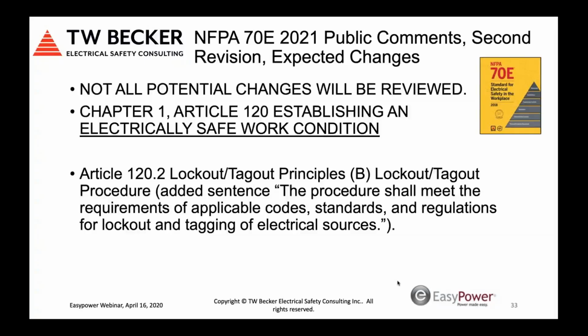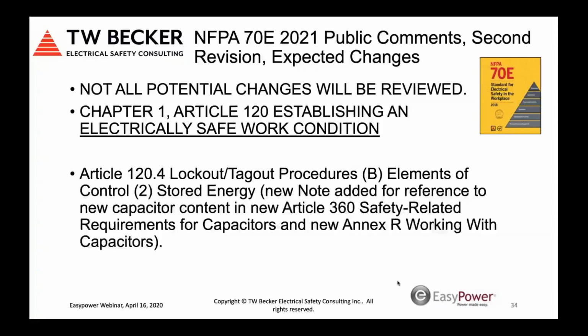Article 120.2, lockout tagout principles, lockout tagout procedure. It added a sentence that this procedure shall meet the requirements of, again, overriding regulations. And the OH&S regulations in North America are very stringent and particular with respect to control of hazardous energy. So it's just really indicating that you may have to meet some detailed obligations. And like I said, that is well documented in occupational health and safety regulations in North America, and I would anticipate globally as well.